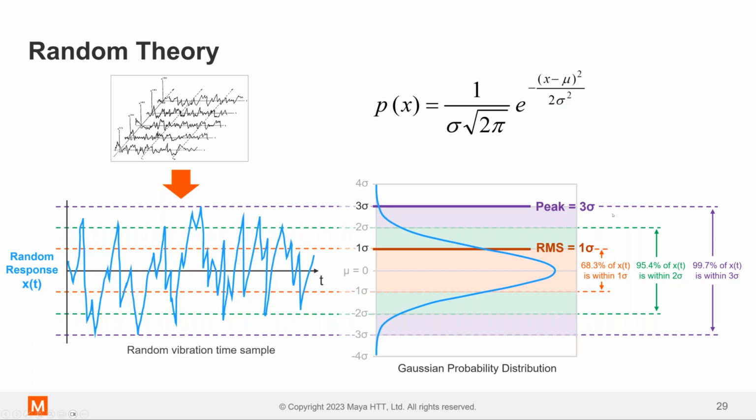On the other hand, at 3 sigma, we can live with not designing for that 0.3% probability. And then you add safety factors on that to cover, but you can't always necessarily design for 100% of loads, so we choose the 3 sigma level. So we're 99.7% confident that we've designed for that much of the loading.